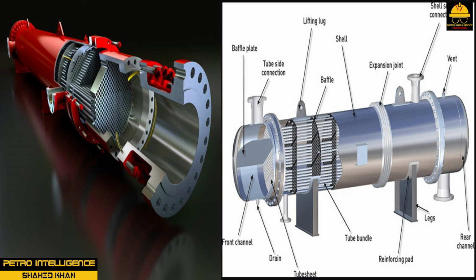or U-tube. On a fixed head heat exchanger as shown in picture, tube sheets are attached to the shell. Fixed head heat exchangers are designed to handle temperature differentials up to 200 degrees Fahrenheit or 93.33 degrees Celsius. Thermal expansion prevents a fixed head heat exchanger from exceeding this differential temperature. It is best suited for condenser or heater operations.